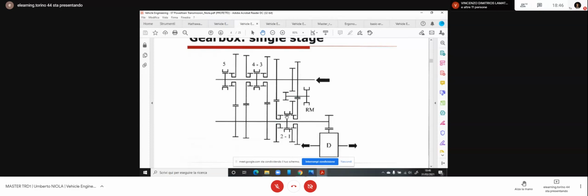Please note the interesting thing is you do not need to always have the free gears on the input shaft. You can also use the secondary shaft. The important thing is you don't need to have permanently in contact the two gears, because this is always a single ratio engaged.